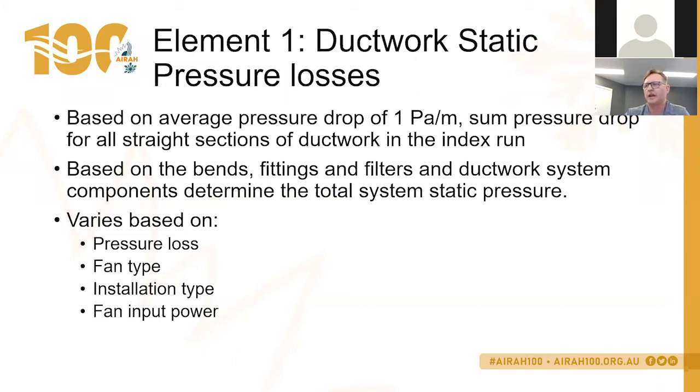You also then have to take into account fittings, filters, coils, etc., to determine their static pressure losses. And there are maximum allowances within the code that you use.